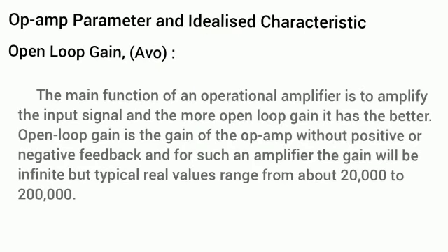Op-amp parameters and idealized characteristic. Open loop gain. The main function of an operational amplifier is to amplify the input signal, and the more open loop gain it has, the better. Open loop gain is the gain of the op amp without positive or negative feedback, and for such an amplifier the gain will be infinite. Typically real values range from about 20,000 to 2 lakh.